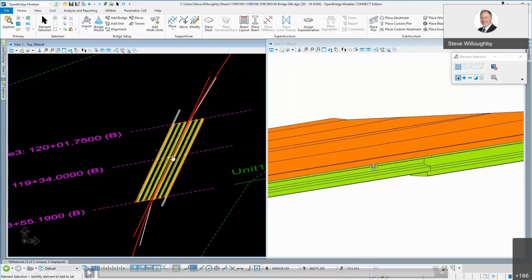So you'll probably need to use some kind of an offset here to get that pier to come in the right location. And when they're skewed, that adds a little more math on your part to figure out that length, because you may know the distance radially, but that distance is actually along the skew line. So you'll have to take that angle into account, maybe do a little more math to figure out precisely how to get that pier or abutment placed in your model. But it's not anything that any of us can't do, and it just takes a couple moments, and you can get that precisely where you need it in your model.